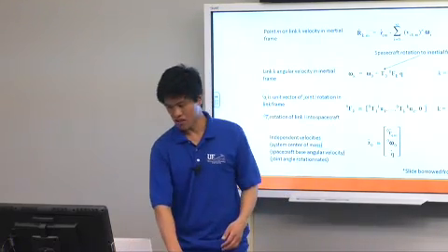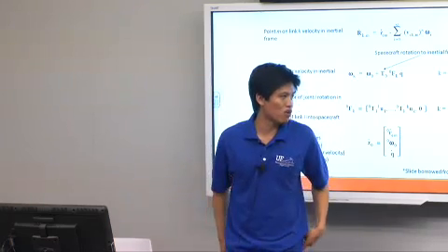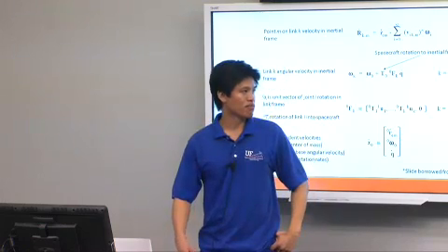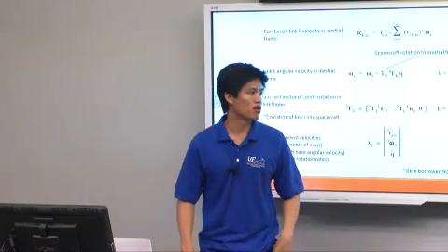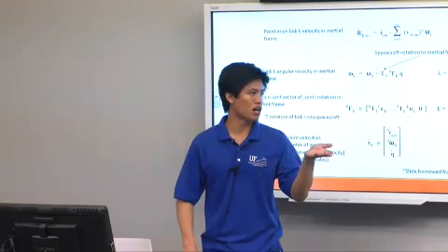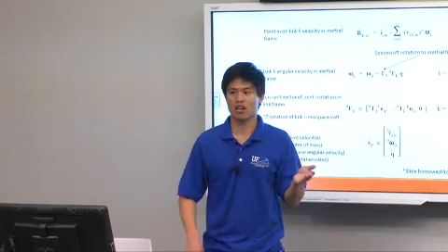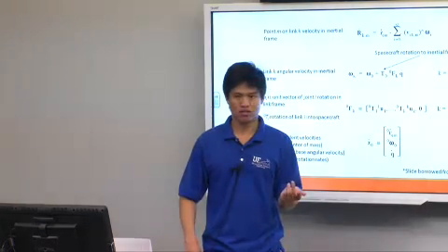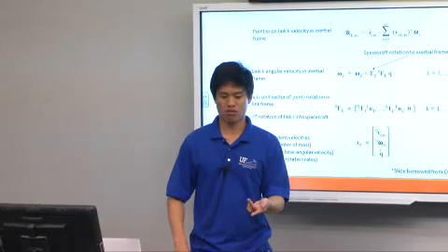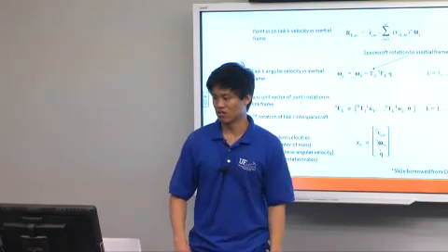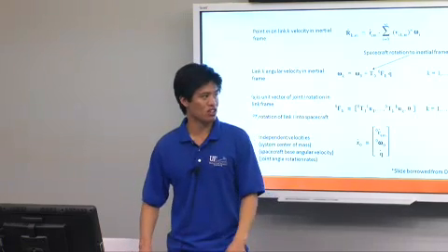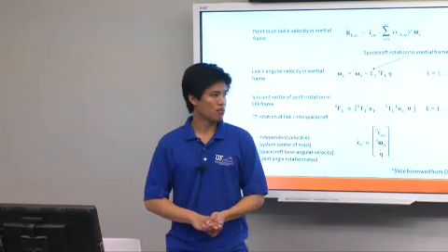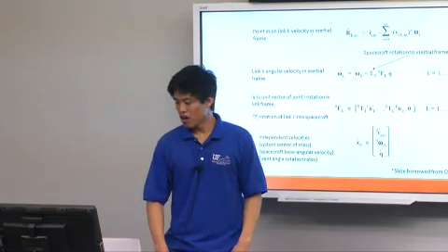But okay, so again, these are the vector quantities, and this represents our velocity, I guess, of an arbitrary point, how we would transform back. All these quantities are important when we write our kinetic energy, which is 1/2 times the inertia times velocity dot velocity. I mean, I'm being informal, but you know the definition. And so that's for a rigid body, right? That's for a rigid body. Yeah. So for a system of bodies, it's the summation.